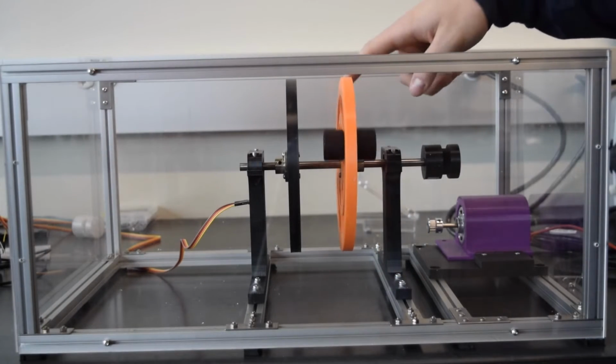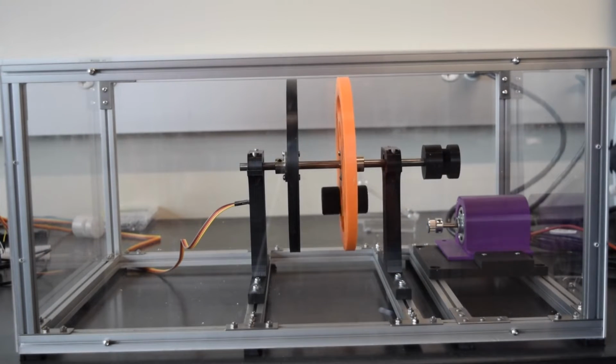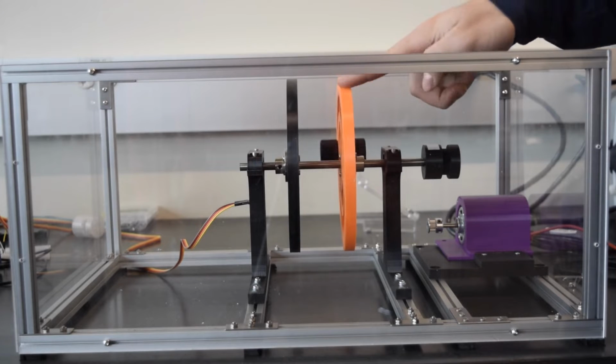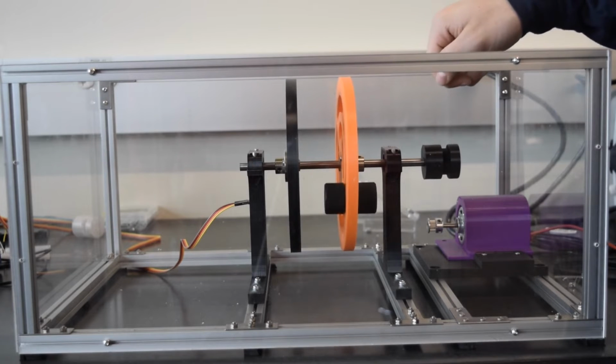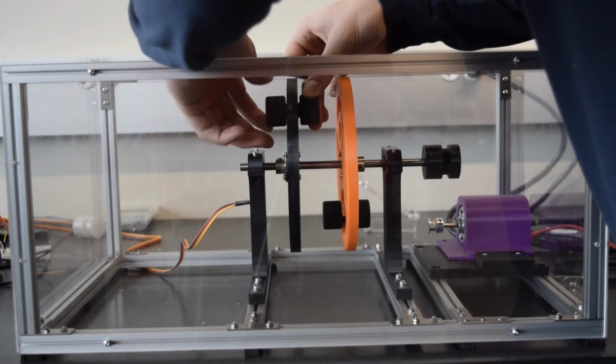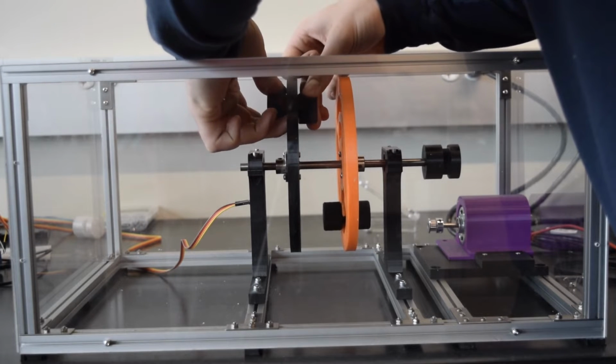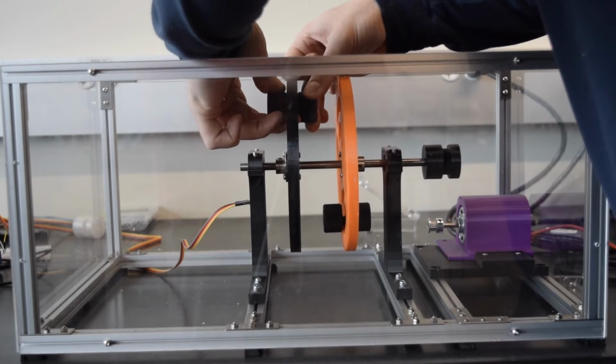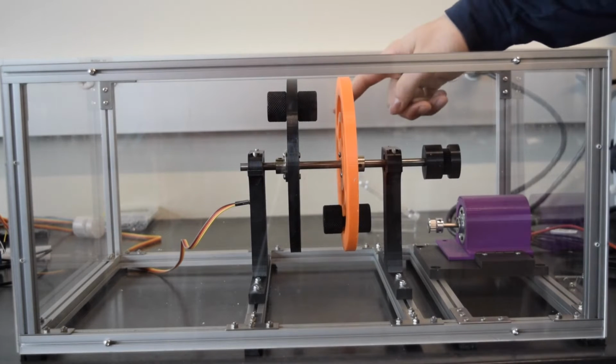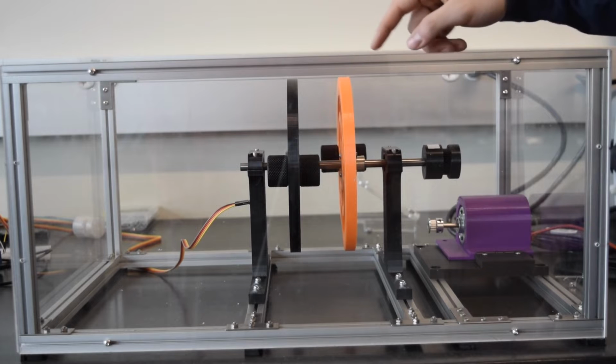The student is now observing the properties of the static imbalance and must figure out how to correct it using the correctional plane and mass. An equal mass is placed on the correctional plane at the same radius with a 180-degree shift, which will introduce a statically balanced but dynamically imbalanced scenario.